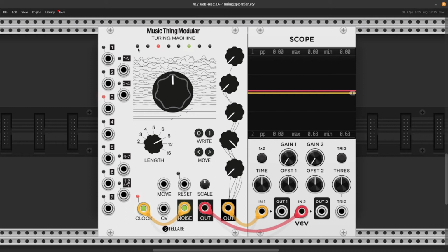We also don't know if the most significant bit will be high or low, so let's also throw that up there, but we know these will have no impact. So we will reclock it again. Right, so this has had no impact because it is still 0, but now, as predicted, we knew that we would have an output voltage being affected by pot number 4, because due to the shift register that high would move from the third most to the fourth most significant bit in the shift register. And what that has meant is we've got an output of 1.997.